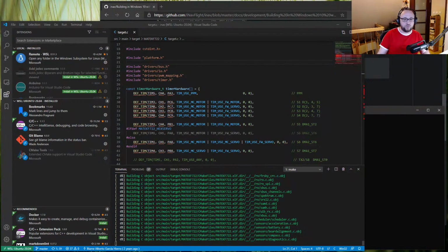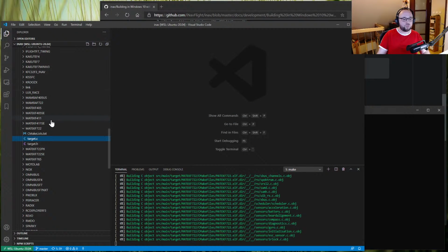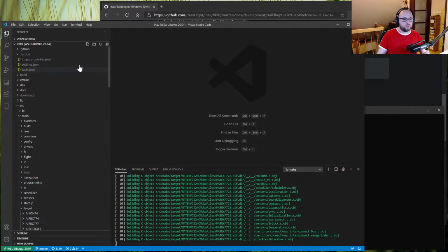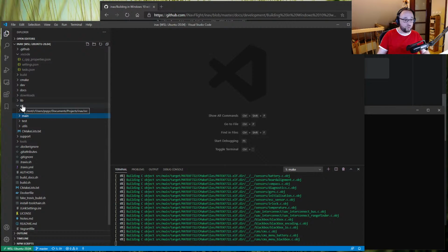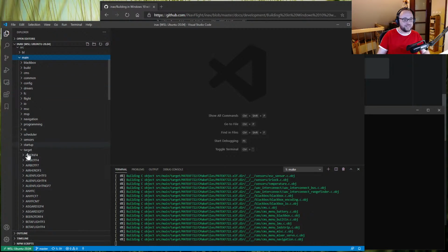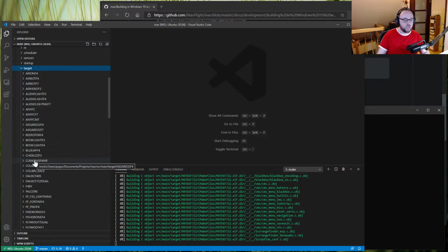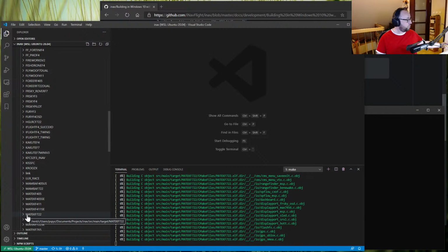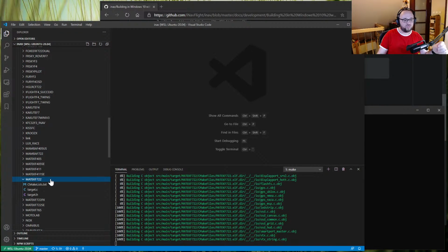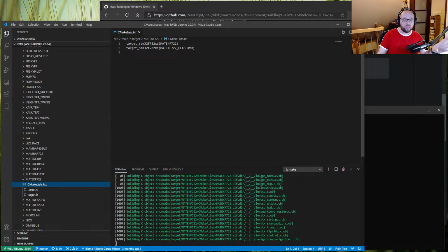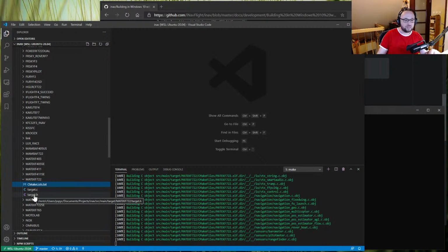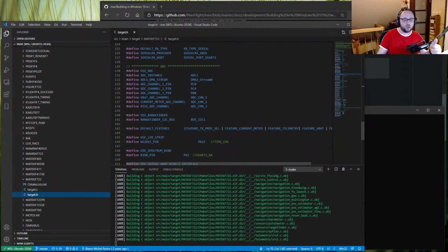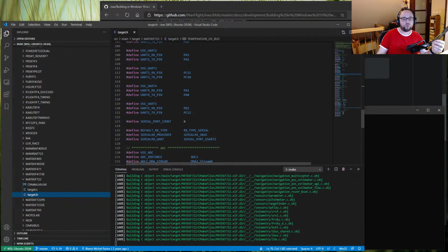Okay, INAV is building right now, so let's go to the quick guide of how to remap motors as servos. When you open the source code of INAV, there are several folders, and the folder we are interested in is called src/main/target. In this folder, there are subfolders, one subfolder for each target. So if, for example, you are using the Matek F722 like I'm using today on my development board, which is right now over here, I will have to open the folder called MATEKF722, and then I will find a couple of files. First, the CMakeLists. This is mainly about the family of the MCU this target is running. You do not really have to change anything. The target.h has the definitions, for example, how many serial ports, to which pins each serial port is connected, and so on and so on.